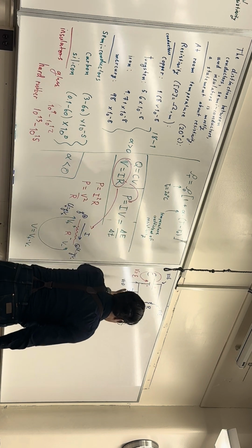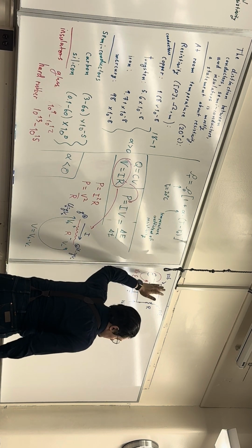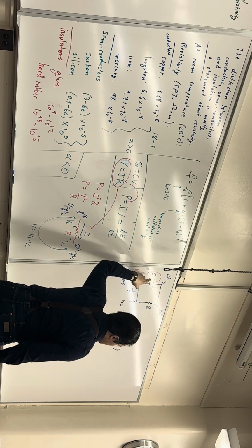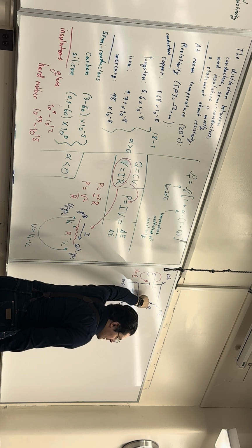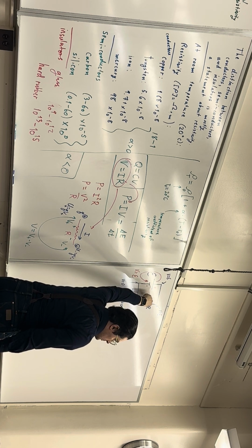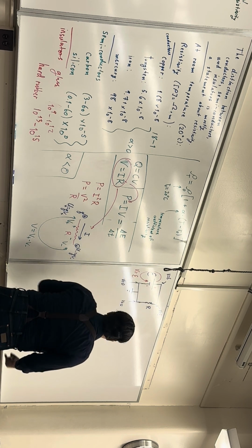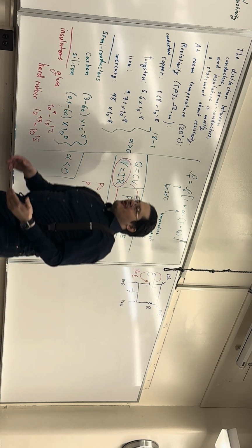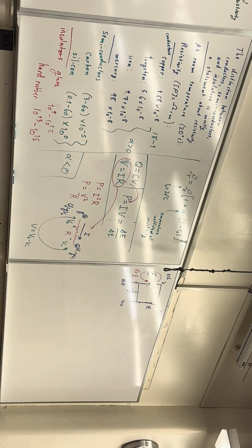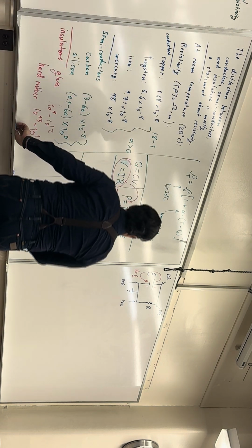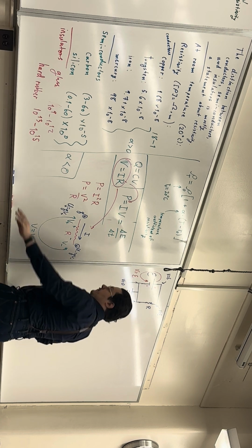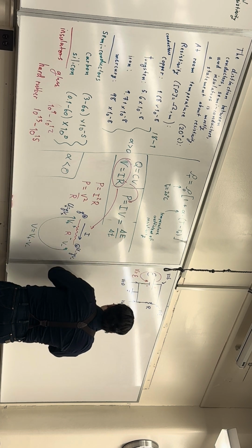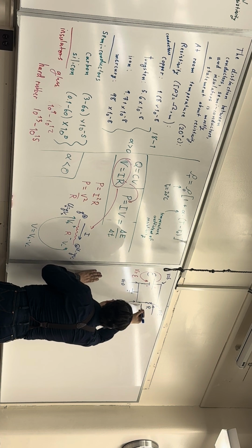It's kind of backward. I have a battery that is, say, fixed at 6 volts. And by hooking it up to a resistor, I'm forcing there to be a 6-volt potential difference. Which in turn means that in order for Ohm's law to be satisfied, a certain amount of current must be drawn out of the battery. So there is an imposed voltage difference of curly E on this side, just by hooking it up to the battery.